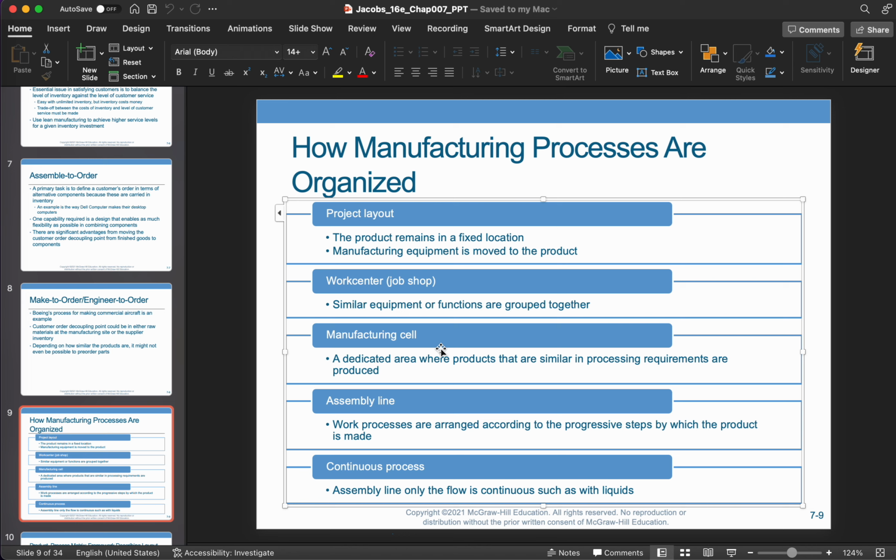there. But you can have many different manufacturing cells throughout the job floor, and you make different kinds of products there, and that way you can make more products than with the job shop, because in a job shop every item has to move from location to location to location, so all the transit takes time. You need to have a lot of inventory buffers. But with the manufacturing cell, everything can happen within a single area, and so the productivity, the number of items that you can make, will be higher, right?